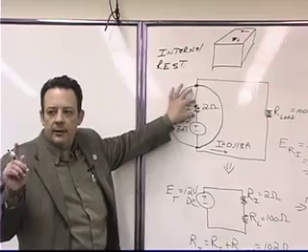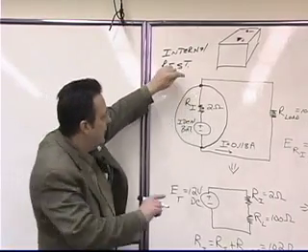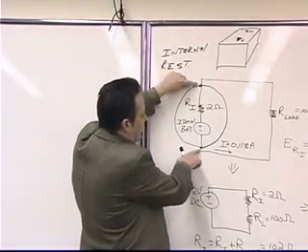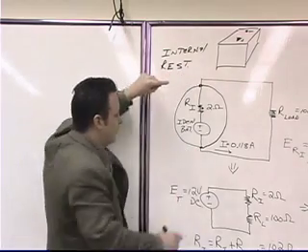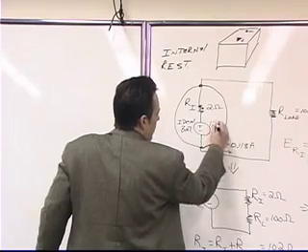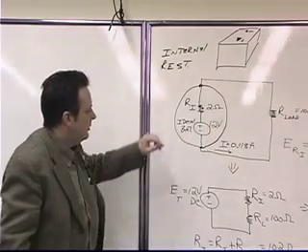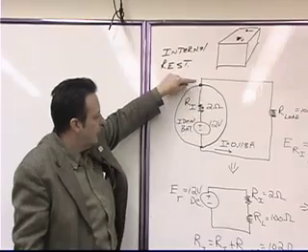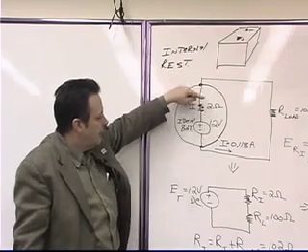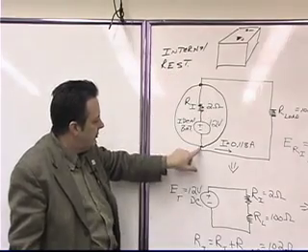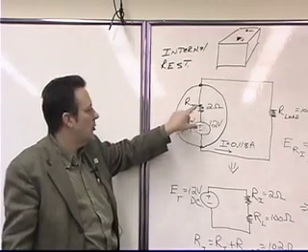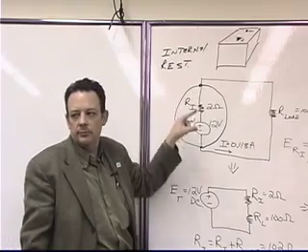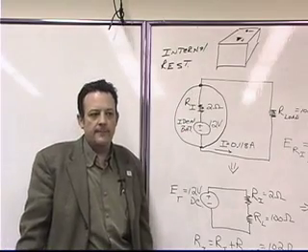What does that mean about the voltage that's available at these points right here? It's lower. It's decreased, right? Because if we started this out at 12 volts, our ideal battery at 12 volts, our ideal battery has been now reduced at these terminals by an amount equal to the voltage drop across the internal resistor. Okay? Is everybody with me on that?